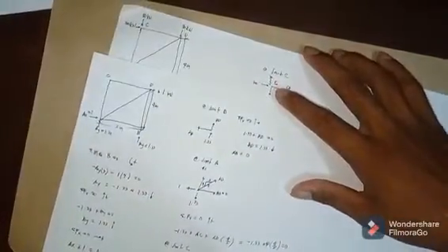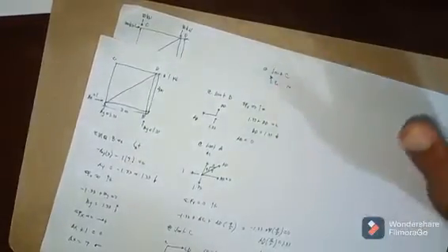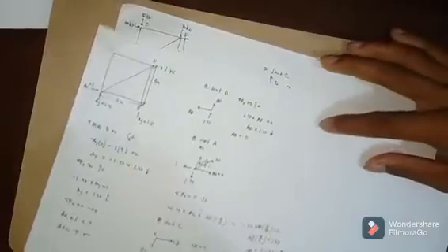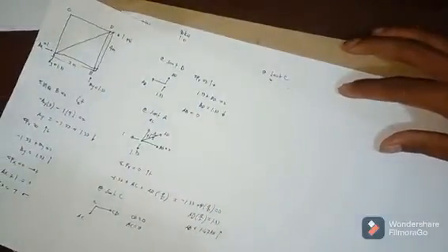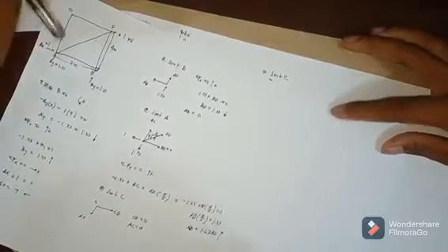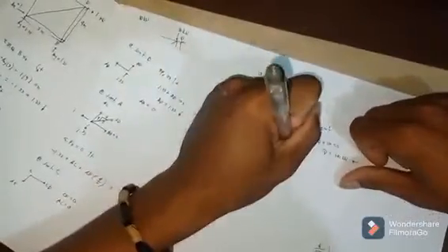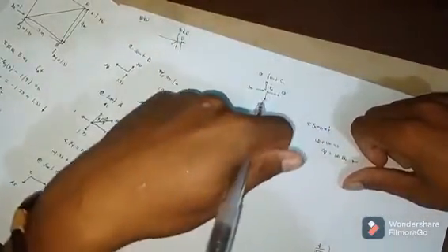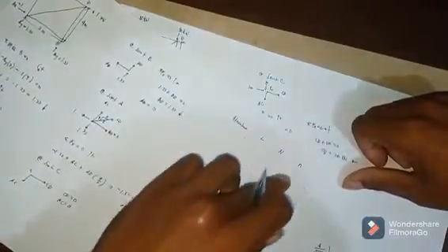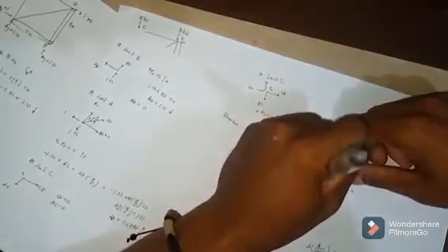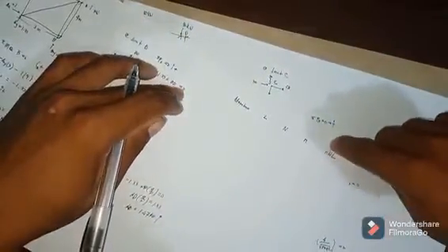So we will tabulate so we can easily determine the problem: the deflection, the smallest cross-sectional area at A. So we write here the member, the length, the forces in the real thrust, and for the virtual, NL, and their total.